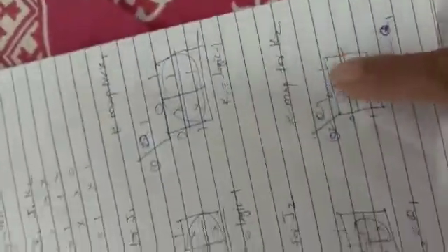Then these J2 values you can enter in a K-map for J2. So here you can combine only these 2 cells. So the expression will be J2 equal to Q1. Okay. Similarly, we can have a K-map for K2, and these values you can enter. So now here also we can combine only 2 cells, these 2 cells, and the expression will be again the same, K2 equal to Q1.